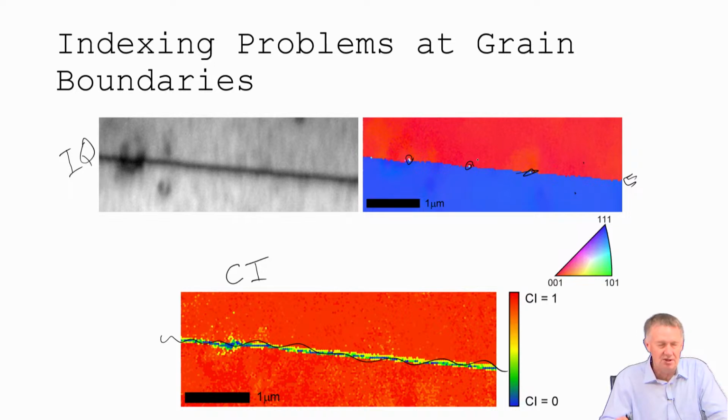So these points are not defined as grains. And then I would do a dilation cleanup where I would just squeeze my boundary together. Right? I just say, make this red and blue touch each other everywhere. And then I have all the information. And in my distribution, I'm not going to get a misorientation that is between this light color.